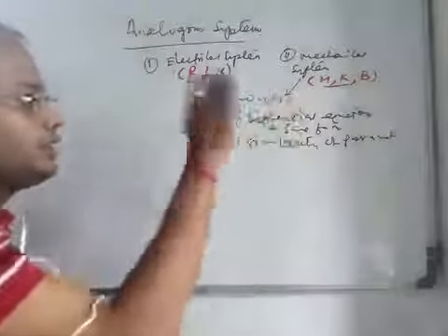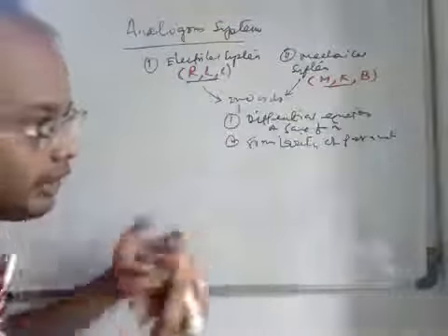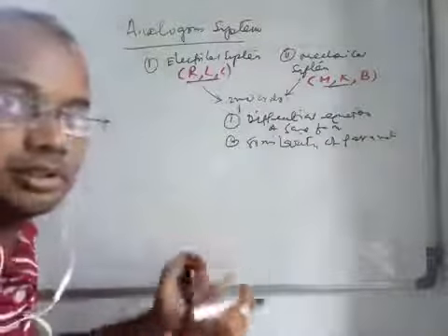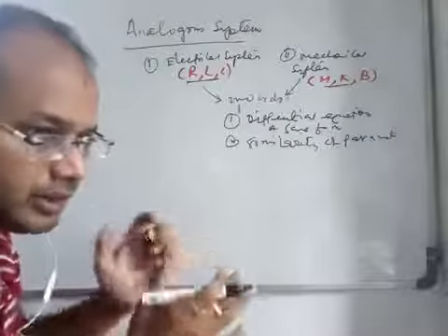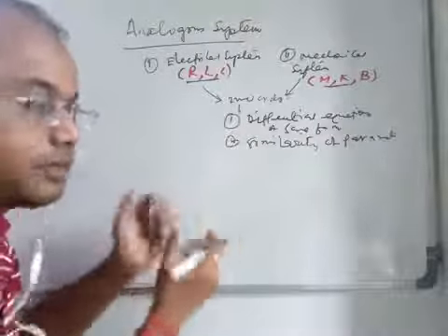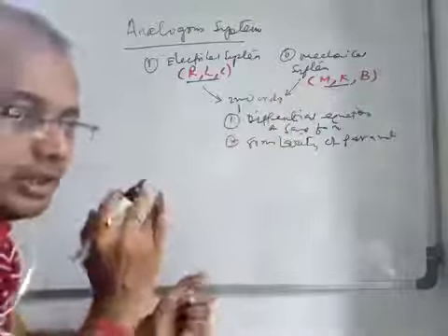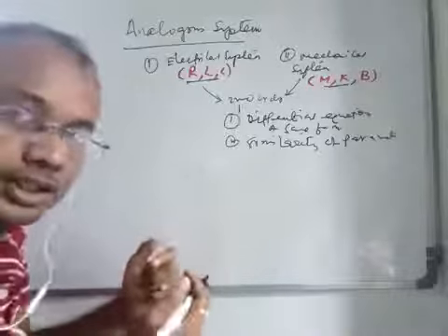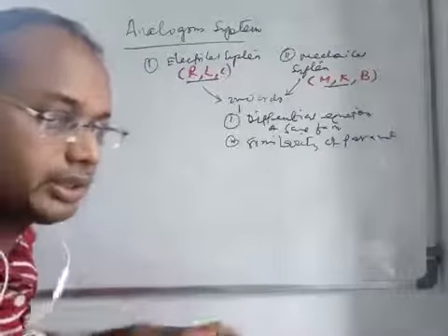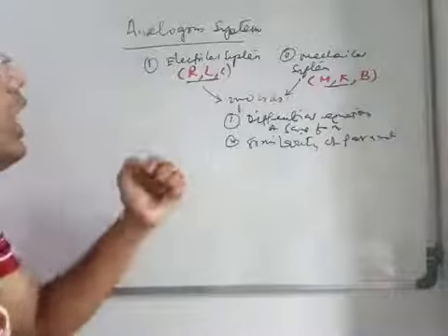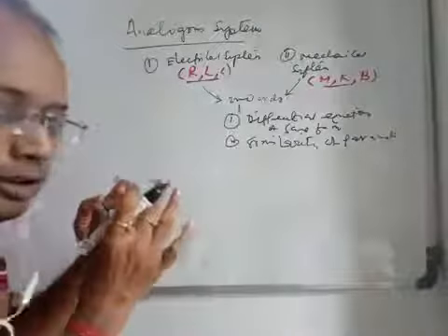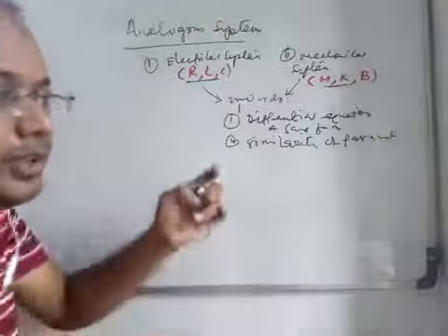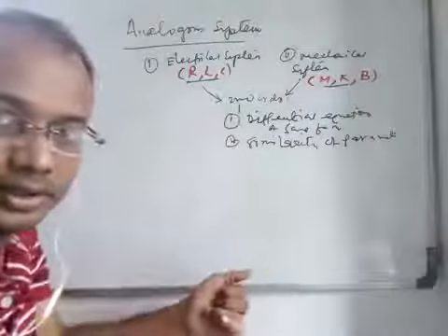Once you get the similarity of the parameters as well as the same kind of differential equations, if one system is given to you, you can get the corresponding other system, right? Say for example, a mechanical system is given to you in terms of mass, spring, and damper. You can get the differential equation corresponding to that mechanical system in an electrical network, right? So the purpose of this lecture is how the analogous electrical network corresponding to the mechanical system can be constructed.